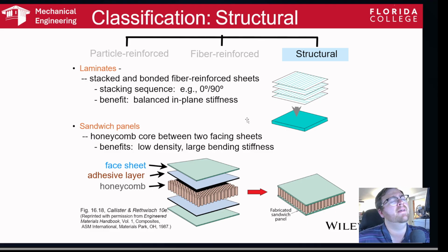Okay, very interesting concept. You actually have to dig really deep into your theory of elasticity to cover that material, and you have to do a lot of working with what's called orthotropicity. Okay, you have orthotropic material. So actually, this 0-90 degree system would be an orthotropic material, not an isotropic material, not an anisotropic material. Orthotropic.